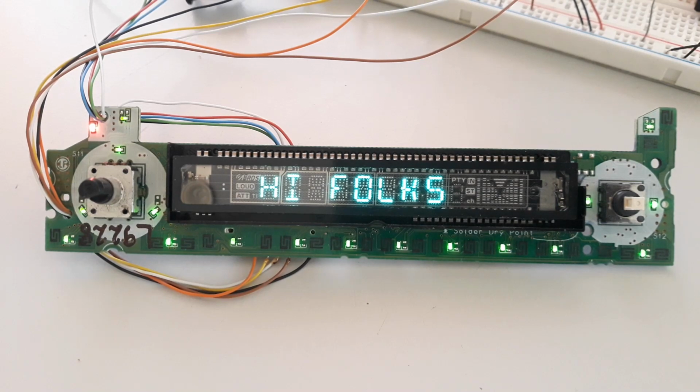We have already discussed several VFD drivers that receive a positive voltage to control the grids and segments, but it is not the most common. The most normal thing is for the grid and segments voltage to be negative in relation to the GND. So I like this detail, as it results in operation with only two voltages as a power source. In this case, 3.3 volts or 5 volts for the logic voltage and the filaments.